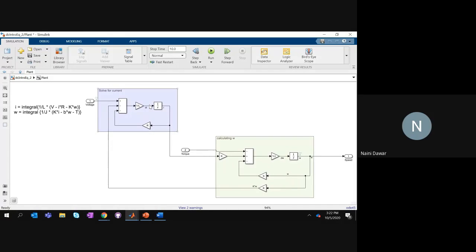In that case we have a data-driven modeling approach, and that's where parameter estimation comes into the picture. We give the input and the output response and run the estimation. At the back end, Simulink runs the optimization techniques, and as a result it gives you the values for all these parameters: what is R, what is L, what is J, B. It gives you the values of these parameters corresponding to the simulation result from the hardware that you have captured. Does it make sense?